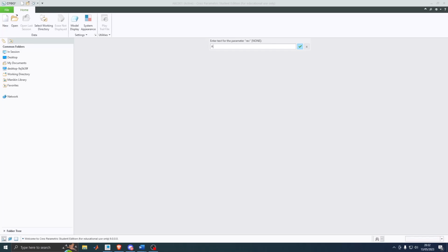So, revision is the first revision. Release status, that's either approved or declined or pending. Project, so let's say suspension. Drawn by myself, so Nui Does Engineering. And then material, let's say it's steel. We can be more specific: 1020 CDS, so cold drawn steel. Surface finish, none. Title, so what's going to be the title for this part, and we can call it strut, or tube.